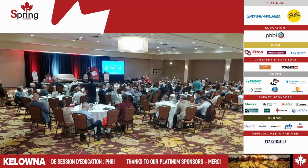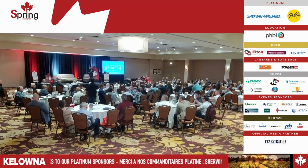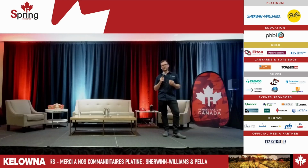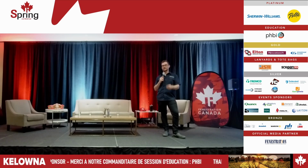Sorry, say that last section again. He's asking about a comparative analysis of sliding windows compared to casements or tilt-turn systems and the air leakage concerns. Anytime we're doing whole-building air tightness testing, we always see leakage associated with sliders. Compared to a lift-and-slide patio door or casement windows, those always perform better. But we've done projects with full sliding glass doors and windows and are still consistently hitting our targets. Sliders are always a weak point for air tightness, though.